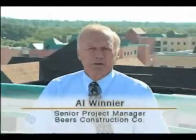Let's hear what others have to say about autoclaved aerated concrete. We're pretty enthusiastic about it. We had a very poor soil condition. The weight of this project being lighter than normal masonry allowed us to put in a foundation system much more economical than we would have needed with conventional masonry construction. The flexibility, the ability to design block walls, single wide masonry, without having to deal with putting anything else in front or in back of it.